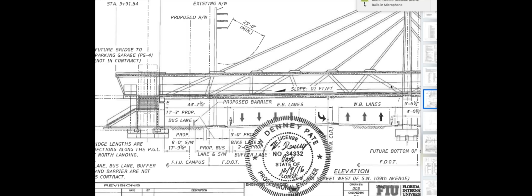These cannot, this is concrete, can't deflect. So if you imagine if you were trying to bend this, if this went down just a little bit, you'd get cracking right here inside these joints here and here. We're only going to refer to these 2 joints because we don't have to refer to these. But it would be compressive cracking, and then it would also be coming outwards in the back side here just ever so slightly. So you would have some cracks on the back side of this. As this was still pushing downwards, we'd still have some cracks in here. But we have none.